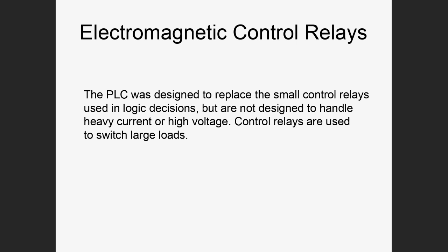I'm going to start talking about something we've already mentioned early in the semester, the relay. There are relays that we use for logic, called control relays, and then there are these heavy-duty relays we use for interfacing machines or devices to the PLC. As you are aware by now, PLC relays have been replaced by solid-state devices. But back in the old days, they used relay contacts, either in series or parallel, to represent AND, OR, NOT logic. We can use normally open and normally closed contacts to represent NOT.